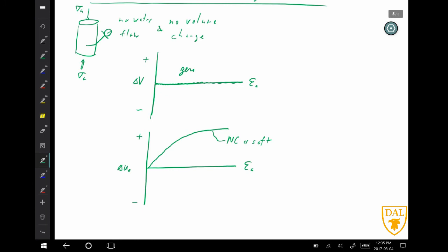So you imagine it, the grains want to contract. All the voids are fully saturated, full of water, and the water cannot escape. You're shearing it. It wants to go to a more compact state, but it just cannot. And so there's a pressure buildup inside of the pores. We're increasing excess pore pressure. So it wants to contract, but it can't.